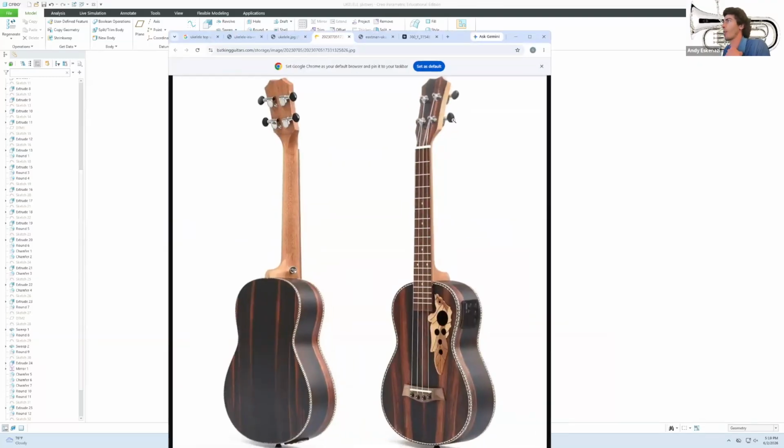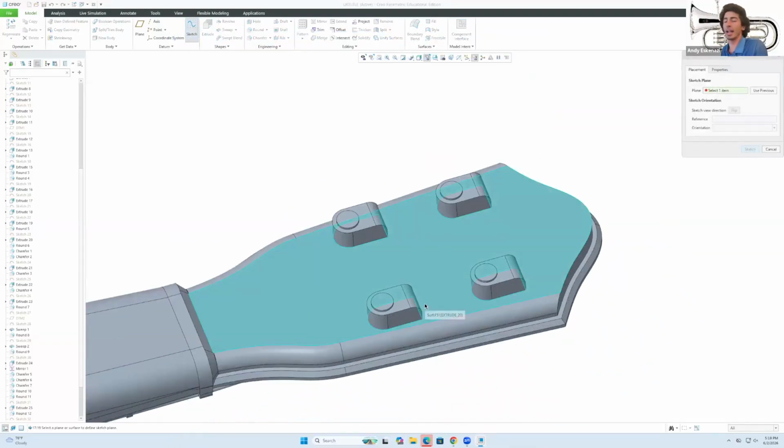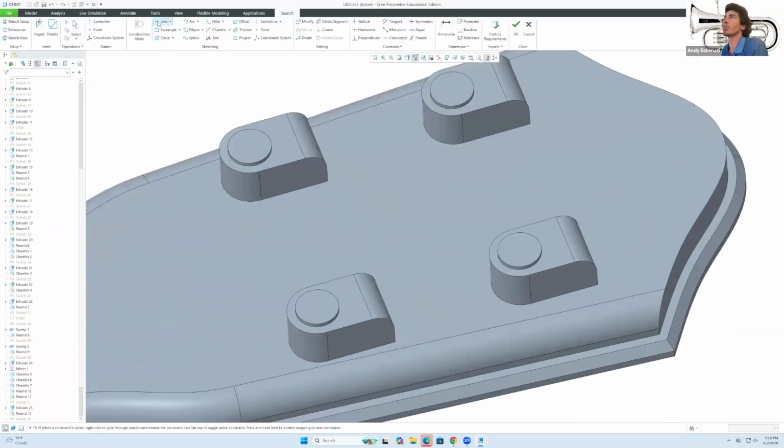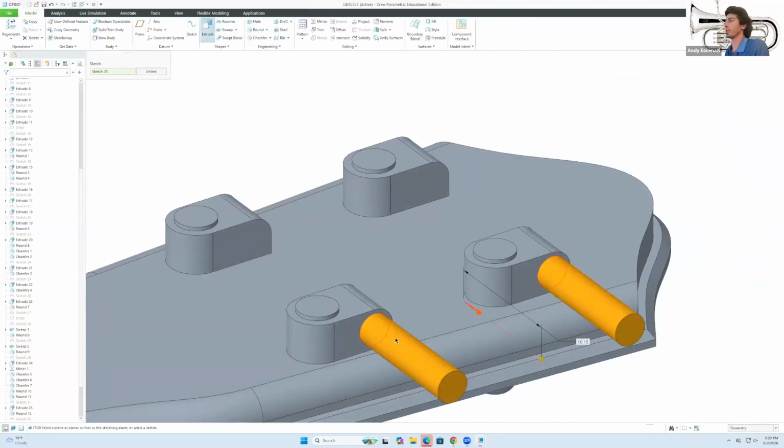But the most important thing is that now we could extend a little circle from here. So how do you do that? Well, the first thing is I'll do it just on one side because then it's symmetric, right? So this should be easier. So I'll go here to construction line. Excellent. So I'll just bring it all the way to that point. And now we'll do a circle, oh, not that big. We'll do 2 circles. And we can make these 4. And now we'll say okay, extrusion.